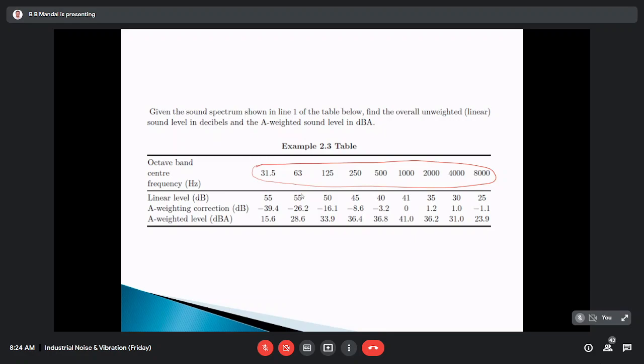That means the digital circuitry divides the entire spectrum into the center bands of the octave frequency, or in the case of one third octave band, it will be further divided into smaller segments like this. So there will be a huge amount of data on the input side, and there you must know what the correction is for.